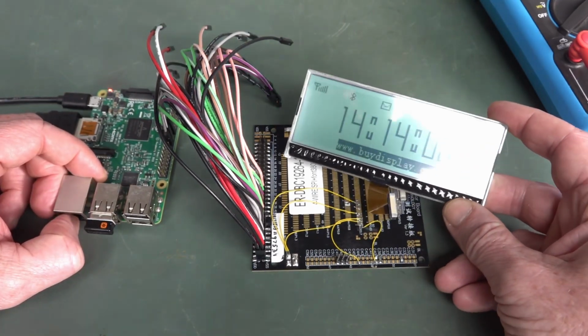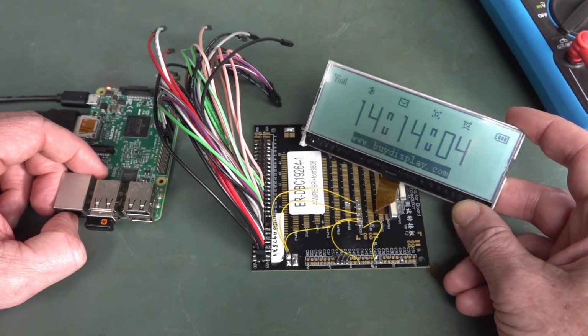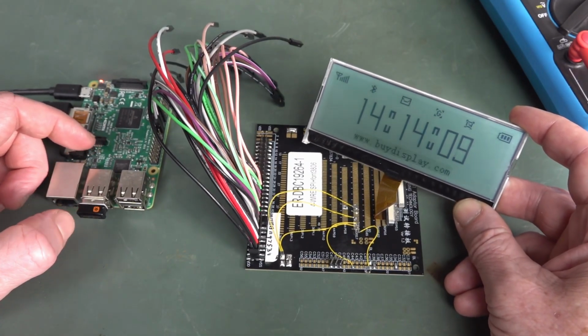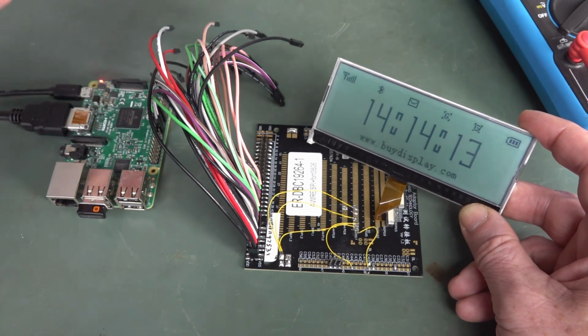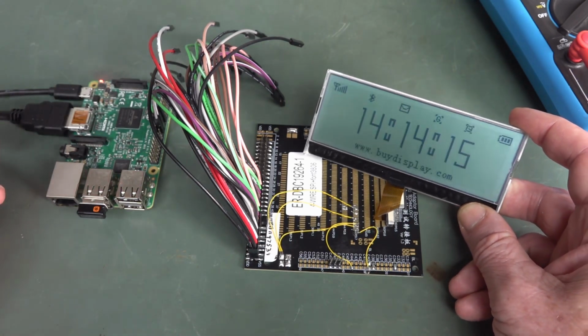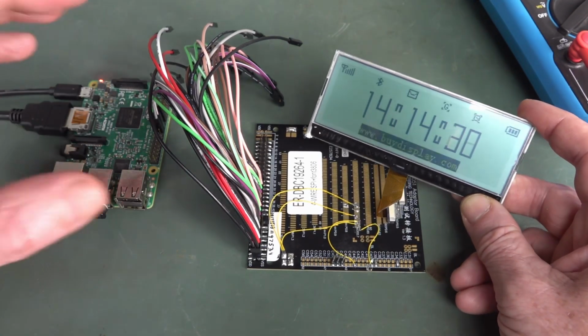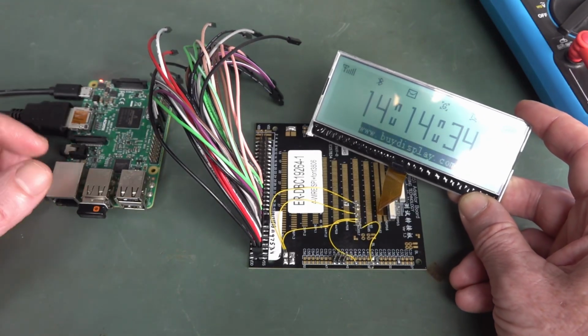But anyway, I want your thoughts and comments on the LCD selection like this. If you've got a better LCD in mind that's cheaper, better contrast, totally reflective. Oh, I forgot, I did actually put the backlight of the other one on, and it's exactly as you expect, but it's like an 80 milliamp backlight. So I would prefer a 100% reflective LCD, which should give better contrast.